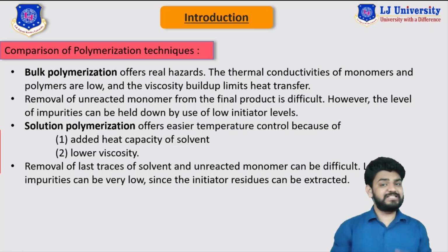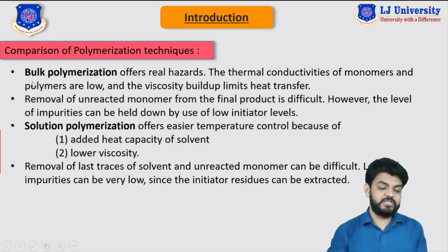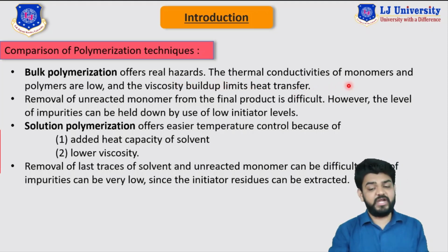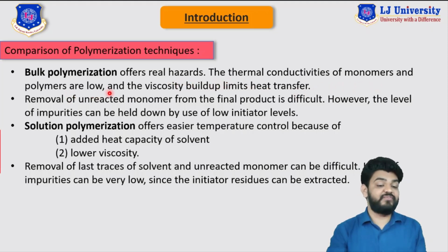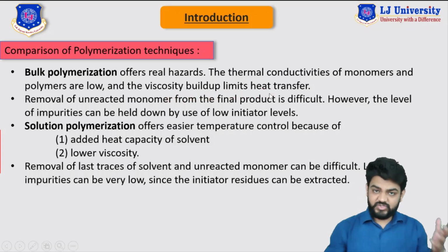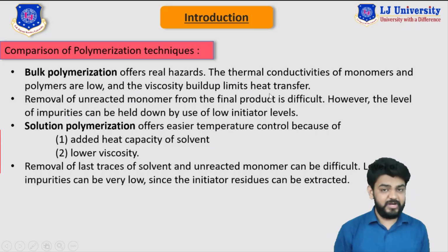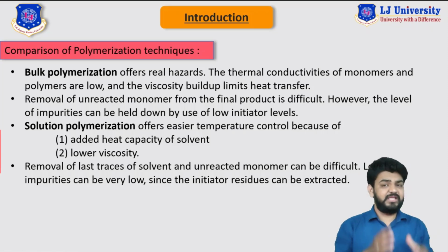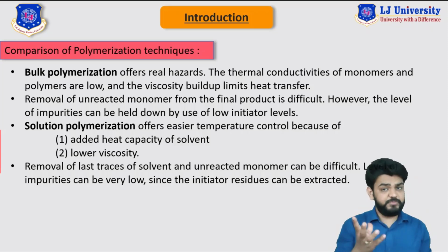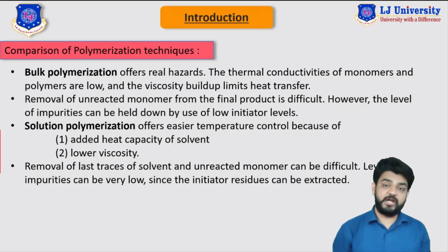So as you can see on the screen, bulk polymerization often leads to hazards. The thermal conductivity of monomer and polymer are very low, and the viscosity buildup limits the heat transfer. As we have already discussed in the bulk polymerization technique, the thermal conductivity of monomer and produced polymer are very low. So we can say that they are not good thermal conductors.